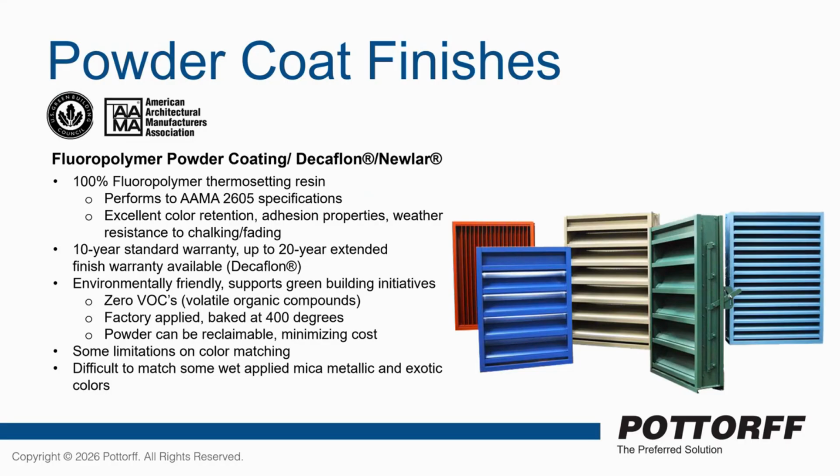And the fluoropolymer does have a better color retention and will have a better weather resistance. I can say that, so it'll have a longer warranty with it as well. It does not have as many options for color matching, or it could be a bit more difficult for some of our powder coating vendors to sometimes do lots of custom color matches. But to my knowledge, they still have a fairly good array of standard colors out there.